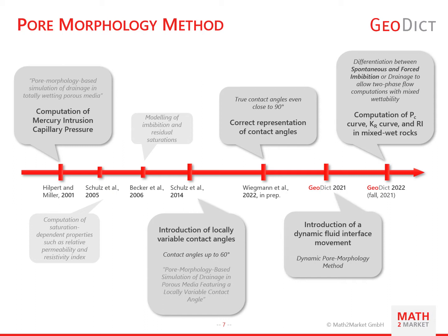In addition, we introduce an extension of a quasi-pore morphology method by a dynamic fluid interface movement, increasing the detail of two-phase flow computations. With these improvements, we may now compute the capillary pressure curve and the relative permeability in mixed wet rocks.